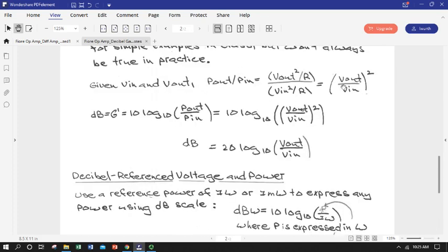Okay, let's just pop this ratio, which is the same as P out over P in, right into our expression for decibel gain, that G prime. So we're going to have 10 times log base 10 of P out over P in, and we're going to substitute our V out over V in squared. Oh, look at this. This is just like our A raised to the X, where 2 is X and V out over V in is A. So this 2 can come around down and multiply by our 10, and we get 20 times log base 10 of V out over V in.